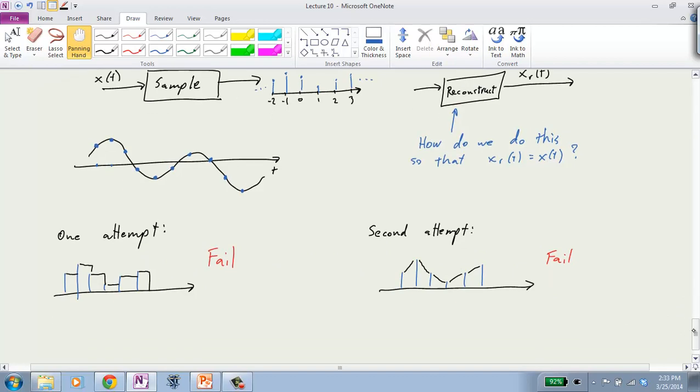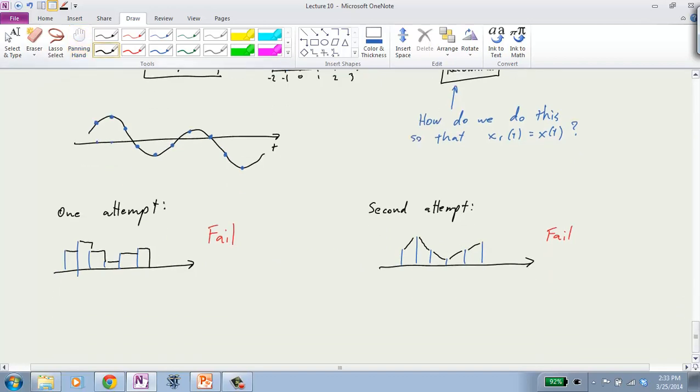By the way, these both can be explained another way. Remember that we have a continuous time way of representing discrete time signals by replacing them with delta functions. In other words, we can take our discrete time signal and put delta functions in place of each sample.